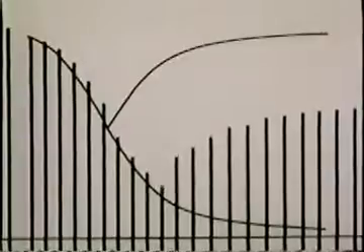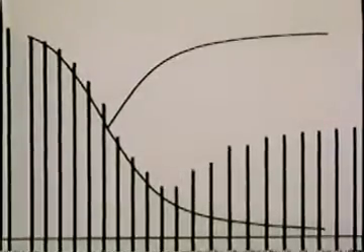For this close-up, we have temporarily adjusted our Schlieren optical system to emphasize density gradients in the flow direction. The control valve is open just to the point of choking, and natural fluctuations in the flow do the rest. Thus, the Mach waves, the low sound level, and the pressure distribution all confirm that the lower theoretical branch downstream of the throat is supersonic, with the Mach number increasing from 1 as the channel area increases.